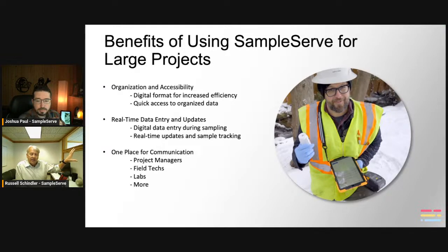and also sorts sample locations from clean to dirty. It'll look back at the historical data, pull up the last time it was sampled, and then sort your locations automatically from clean to dirty, which is a good quality control measure. You shouldn't be sampling the hottest well first at the site. You should be sampling the clean ones and then moving your way down towards the hotter ones. So it just manages all that stuff that people like to do, but it actually takes a lot of time, and it does it automatically in an instant.